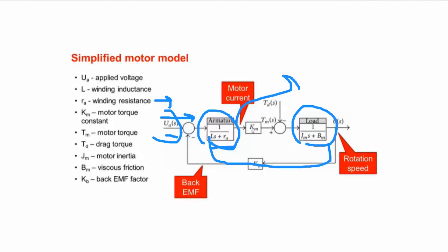For example, in our motors, we have encoder, we have resolver, we have synchronous encoder, we have optical encoder, we have Hall sensor. Okay, generally in military and electrical vehicle applications, we are using resolver. What's resolver? Resolver gives us high resolution position. Generally in electric vehicle and in our design of military grade motor and controller, we are using resolver.